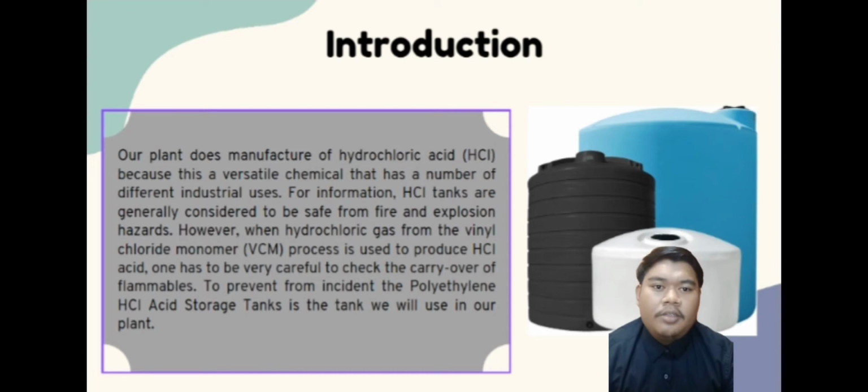We use multiple tanks if the quantity of the acid storage exceeds 12,500 gallons. The acid storage tank should have a specific gravity rating of 1.9, polyvinyl chloride or PVC fittings, Viton gaskets, and Hastelloy bolts. The temperature of its contents should never exceed 100 Fahrenheit.